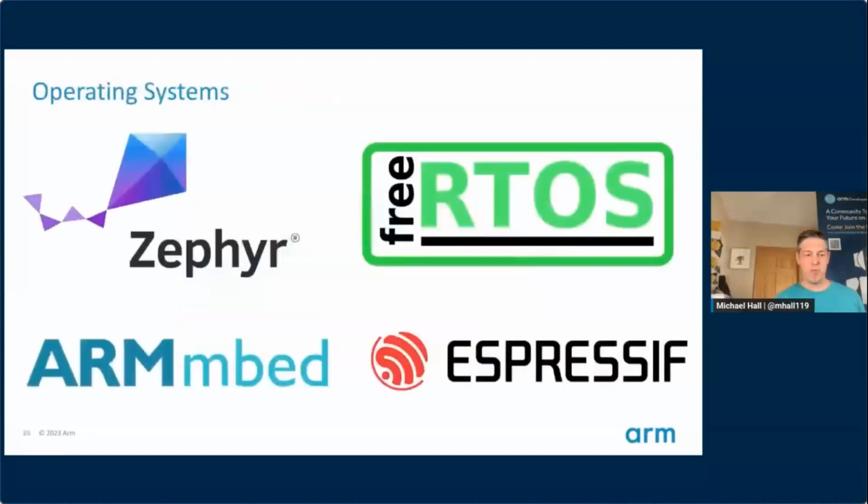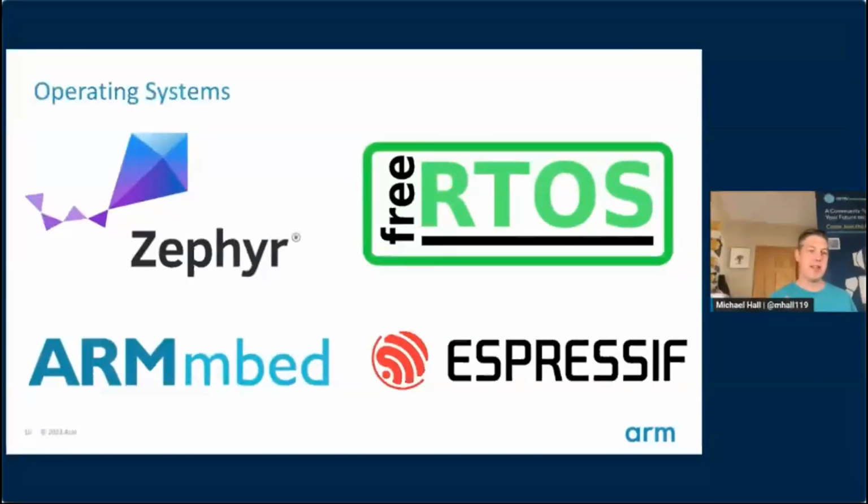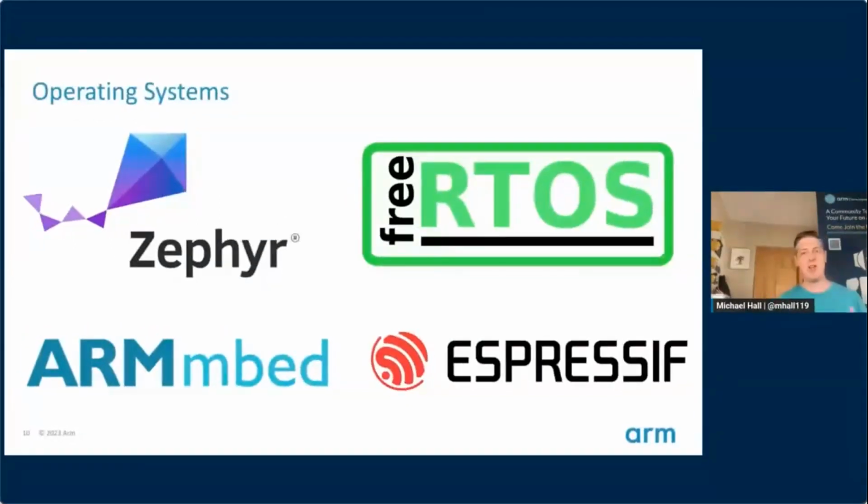There are several real-time operating systems that you can choose from, especially for ARM devices. You can use the open source one, which is part of the Linux Foundation. You can use FreeRTOS. ARM has ARM OS, which is an open source embedded OS that you can use. Or if you're using something like an ESP32, you can use the Espressif RTOS, which they provide for their devices.